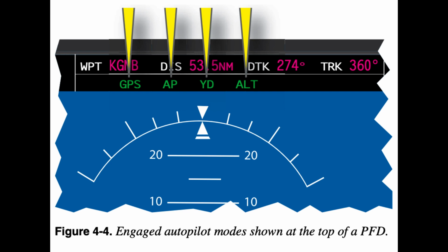Carrying out control movements. Once the FD/Autopilot has determined which control movements are necessary to achieve the flight change, the autopilot has the task of carrying out those control movements. Every autopilot system features a collection of electromechanical devices, called servos, that actuate the aircraft control surfaces. These servos translate electrical commands into motion, the muscle that actually moves the control surfaces.